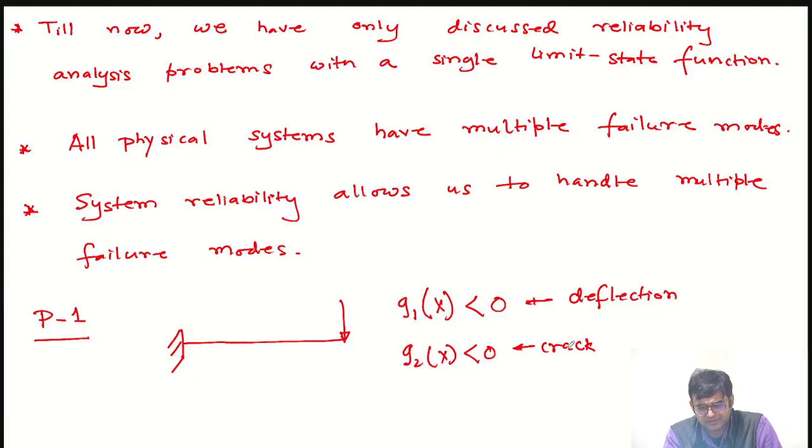Fracture energy is one way, using the fracture energy or fracture toughness. You can think of such measures, some material properties, and if that is exceeded, you can say that it has failed. Some will say that the fact that there is a crack is a failure. Forget about crack propagation. The fact that a crack has generated itself is a sign of failure.